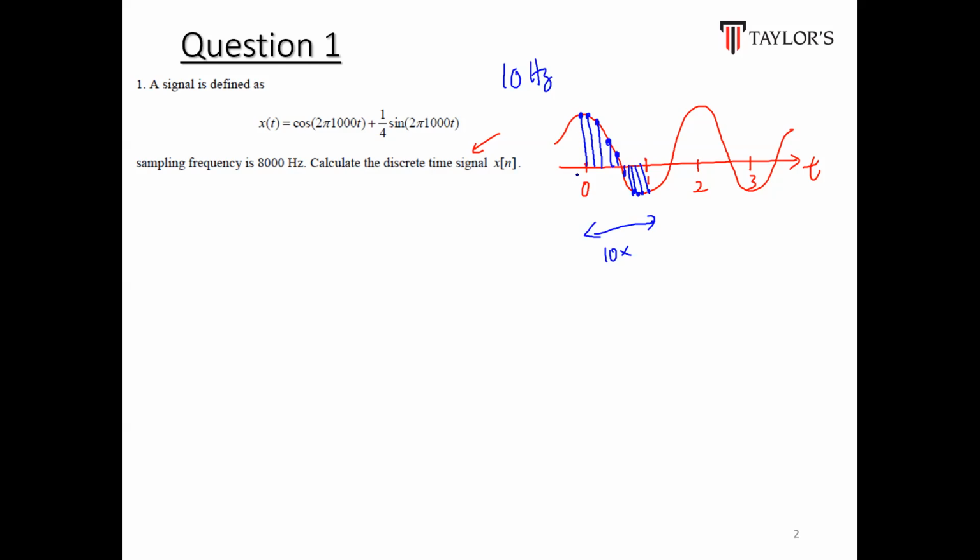So each sample, you will know, is 0.1 second. This one will be 0.1 second, this one will be 0.2 second, all the way until 0.9 second, and then the next one will be 1 second. So by sampling, I'm converting a continuous signal into a discrete signal. This is what I have to do before I feed the signals to, let's say, microprocessors, or into any computer devices.